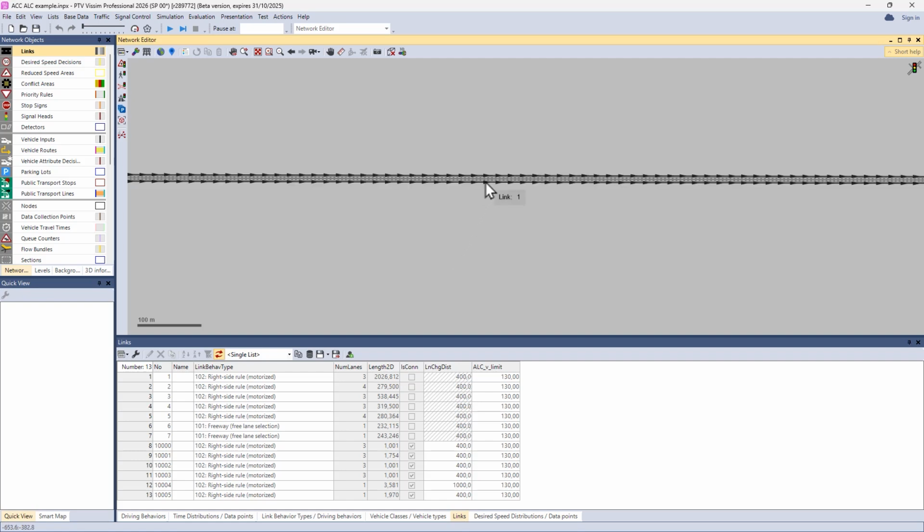So if a vehicle using the automatic lane change considers trying to find an opportunity for applying a lane change, it assumes that just outside of its lookback distance, which represents the detector range, there is a vehicle upstream which goes at a specific speed limit. It has to assume that this is just outside of its detection range and has to consider the potential presence of such a vehicle when considering to go for a lane change maneuver or not.